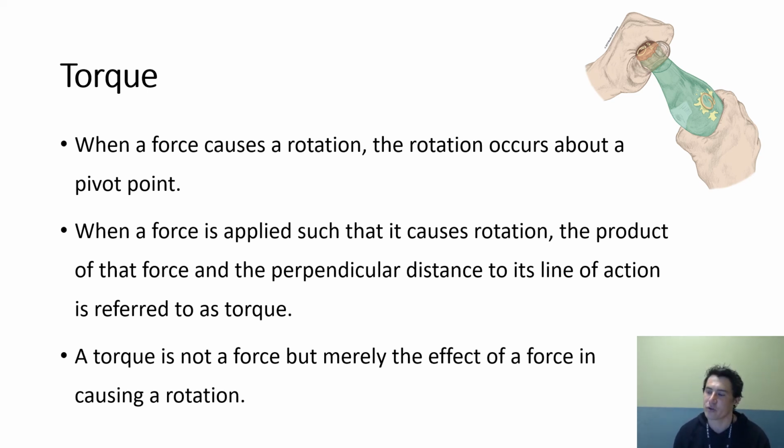A torque is not a force as such. As we said, force itself is more of a looking at the effect, and the effect of force, if we're talking about torque, is that it causes rotation. So that might have sounded a bit confusing when it says torque is not a force. It's more that force can create either linear movement or angular movement. If we think about angular movement, then the word that describes that force is torque.